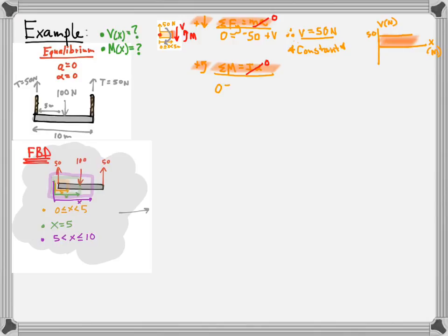It's in equilibrium, and we're going to go from the left side over towards the right side and account for everything that's producing a torque or a moment. We're going to define the left side, where this red dot is, as our axis of rotation. So when we do that, we're going to have 0, and then we're going to come to our moment, and it's in the positive direction by our convention.